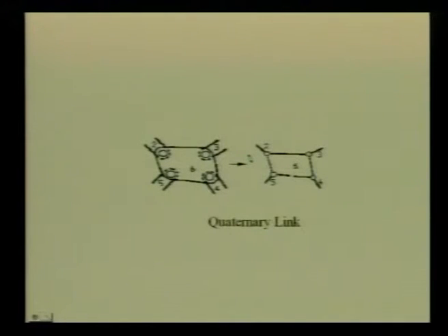This diagram shows how higher order links must be represented. Here, as we see, links number 2, 3, 4 and 5 are connected to a quaternary link which is number 6. Since link number 6 is connected to 4 other links, this is a quaternary link. In the kinematic diagram or the line sketch, if it is represented like this, then there is ambiguity. One may interpret that at this revolute pair 3 binary links, this one and link number 4, are being connected. To avoid this ambiguity, we should hatch this link number 6 to represent that this is a single rigid body and this is a quaternary link connected to 4 other links.